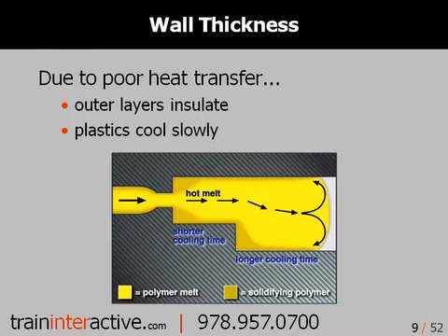Wall thickness. Let's establish a few key points that you should be aware of when working with plastics. Plastics are a great insulator and do not transfer heat very well. For example, we all know how well aluminum transfers heat. This isn't the case with plastics.